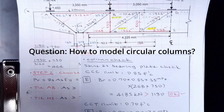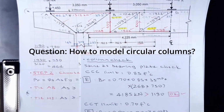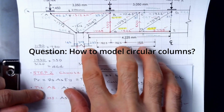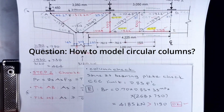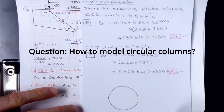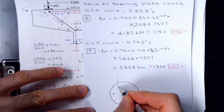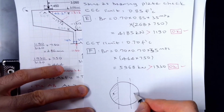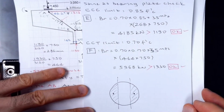I mean, you can approximate it as a square column from the very beginning of the calculation. So that would be my suggestion to you. Do not start with a circular column, because if you want to be super accurate, I don't think it pays off to be super accurate in this situation. So let's say you have this one, you are putting the node here, then, you know, if you want to be super accurate, calculate these areas and then do your calculation accordingly.